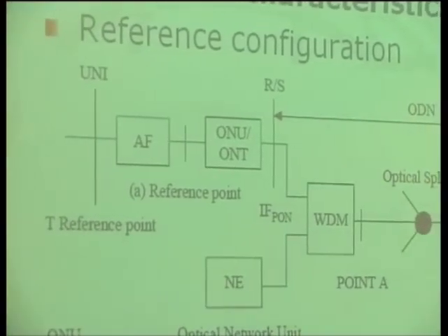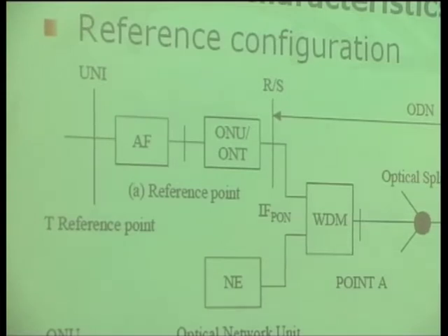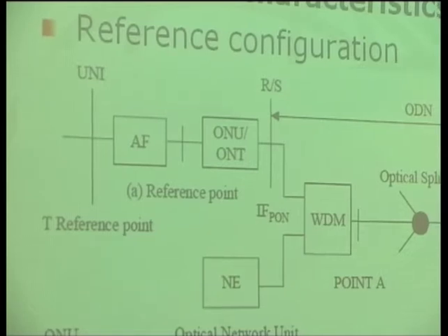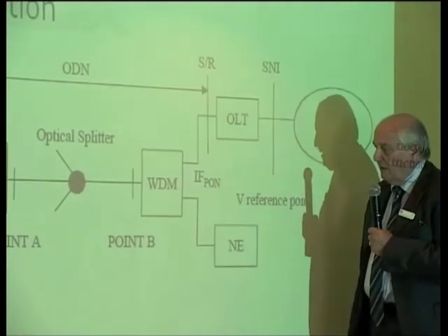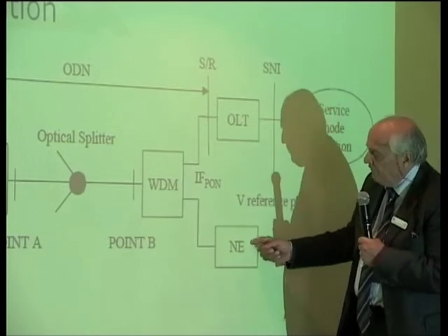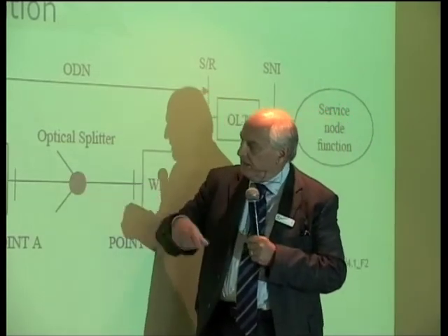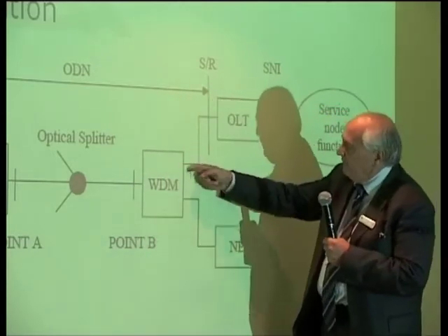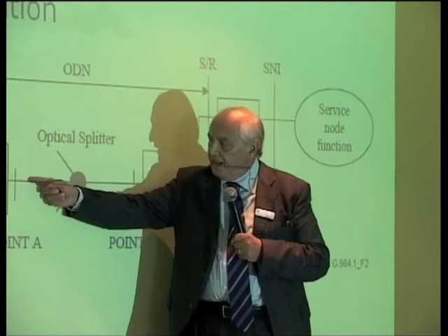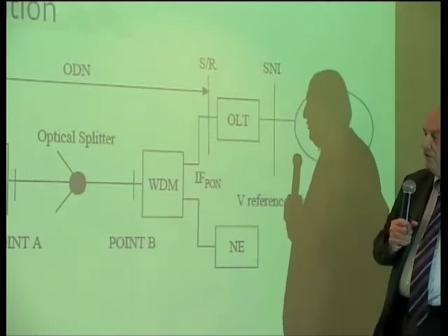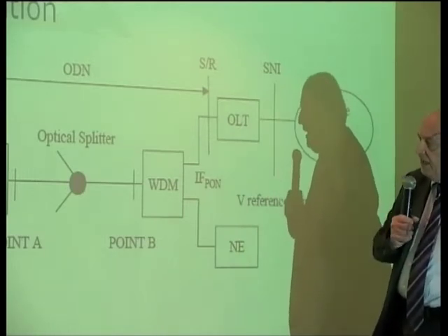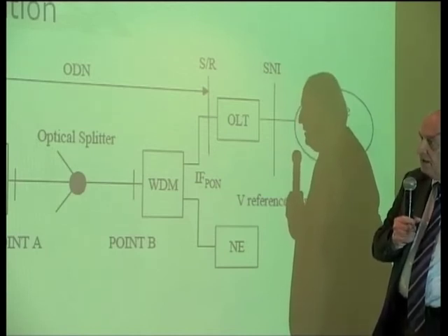To this purpose, some WDM couplers, which are not really WDM multiplexers, they are working in both directions, are inserted into the network. If we pay attention to this WDM coupler, we see that the video will go this direction, the data will go this direction, the returning data will go this direction. So if we use two different wavelengths, we can have a properly working system.